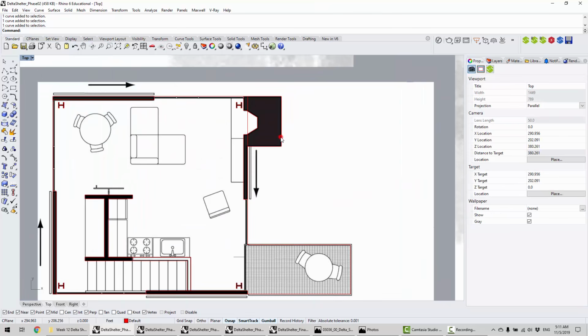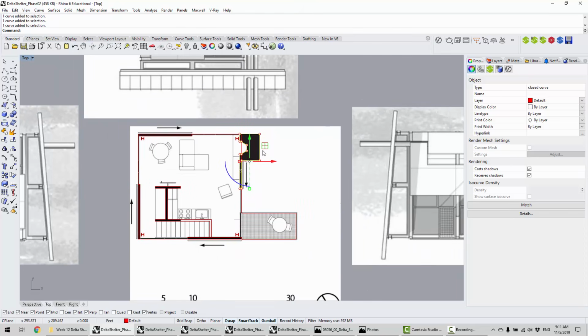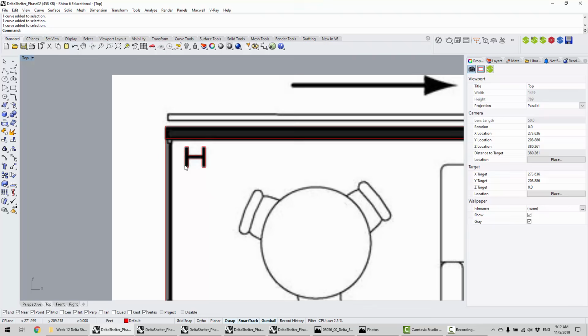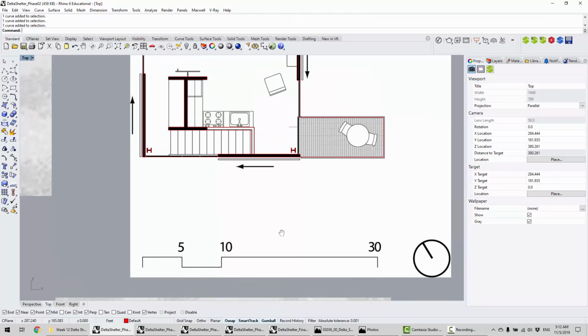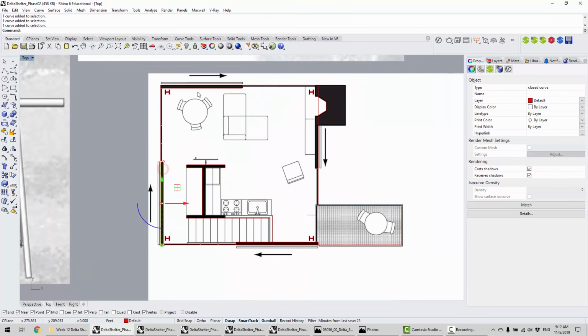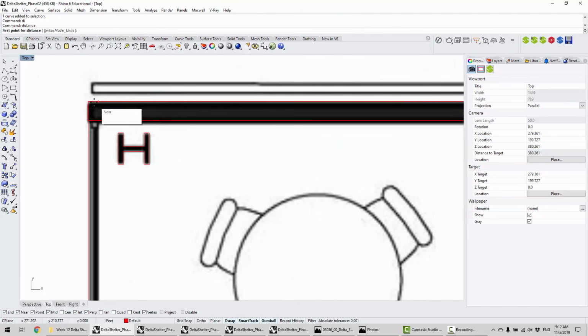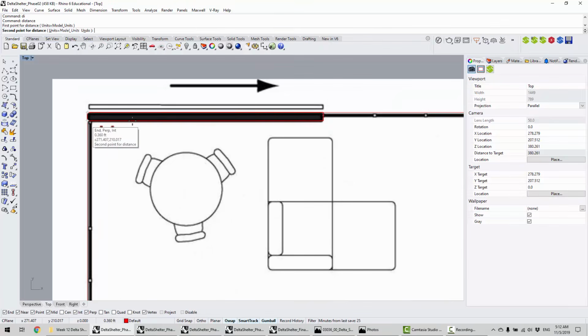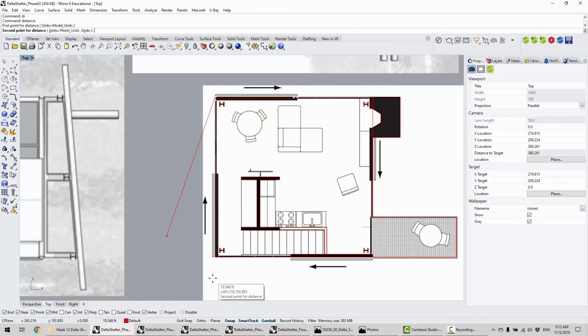One thing to keep in note is that I'm doing the fireplace part on its own, just because it's something that juts out into more of a mass than anything. So you can start doing that, and trace the I-beams and columns that are in here as well. Keep in mind that I try to keep the dimensions of these pretty much the same, because they're actually meant to be the same size. So do rationalize these as you're going along, so that the distances are, you know, 0.36, or this is 10.5 feet. They're not random dimensions.